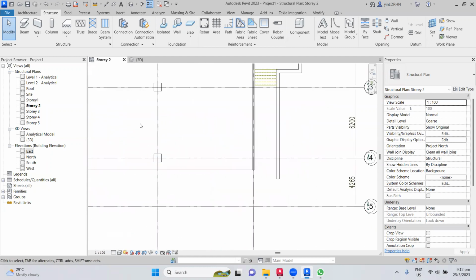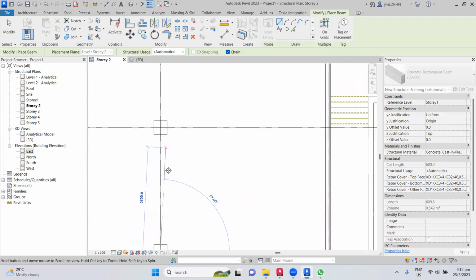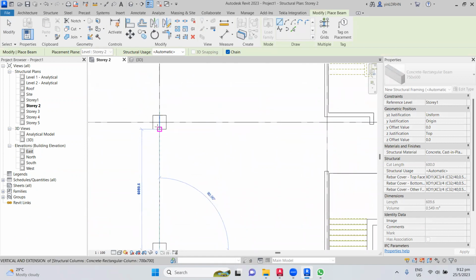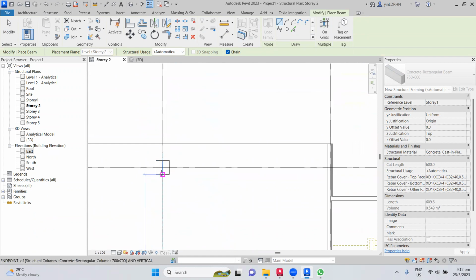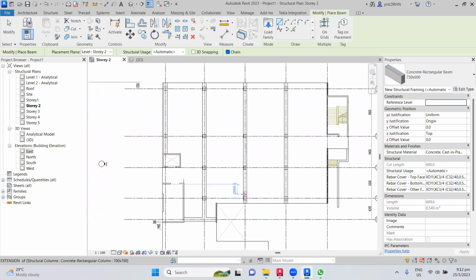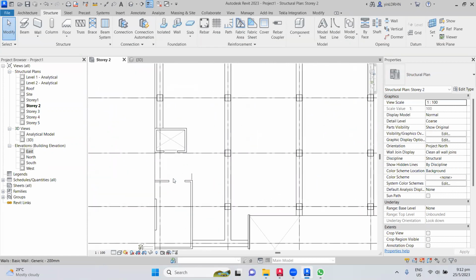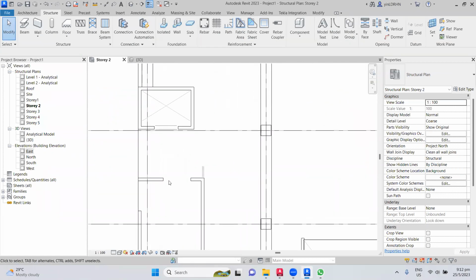Okay. So I quickly do the modeling. Finished. Okay, so now its major elements are ready. You can see this area is quite okay. So here, now here, this beam wall is 200 thick, so I'm going to make it a 200 width beam. So I make it 200 wide and 1000 depth beam.